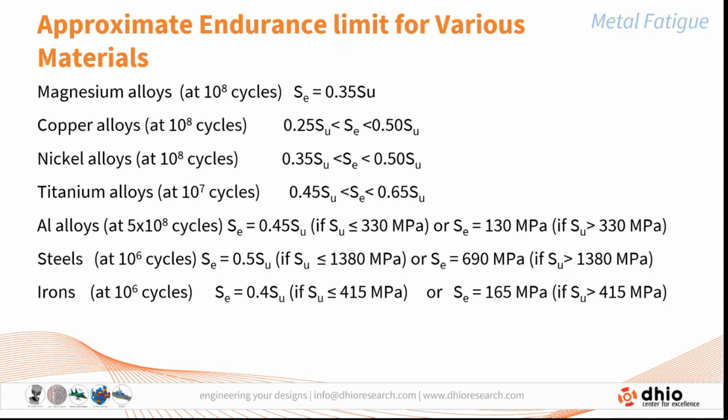For treating the number of cycles and the variable frequency amplitude curves, you have a separate method. We have to adopt that, make it an equivalent constant amplitude band, and then calculate the values. So all these things will have an effect, even though the stress is below the endurance strength of the material.